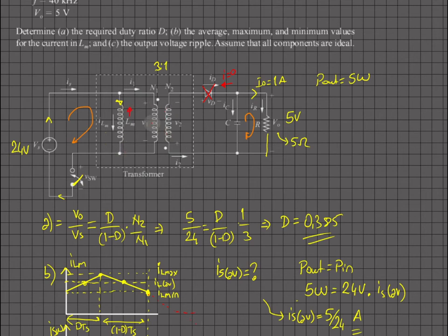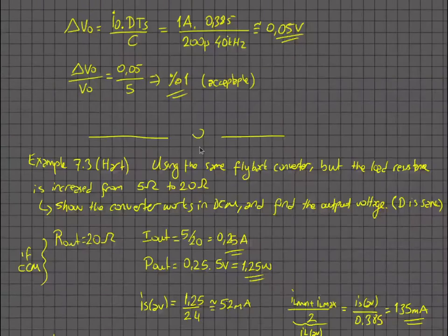So that implies, if you just look at the sign convention, you need to draw some current in the opposite direction. But in that way, you will have the diode reverse biased, and it will cut the circuit, and there will be zero current here, so there will be no voltage to run the LM in the negative direction. So whenever it reaches 0, it will stay there, and the diode will be reverse biased. So let me get the waveforms here and do the rest of the calculations.